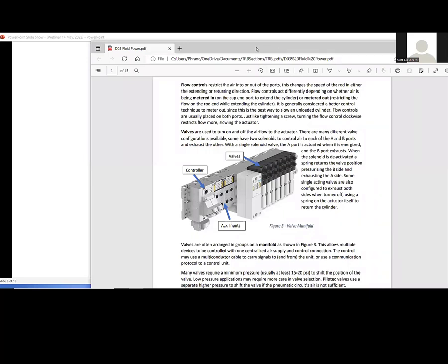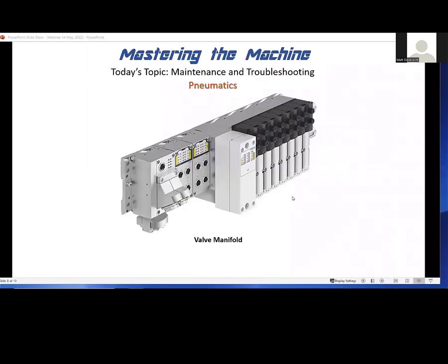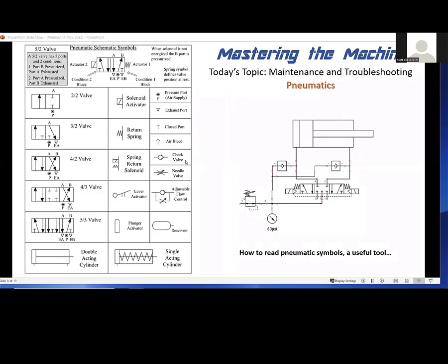So that's a cool kind of valve bank because you can get inputs and outputs from it at the same time. These are pretty common nowadays, where you have your communications to your IO instead of breaking things apart into multiple signals like this, right? This is a valve bank, and I'll show a closer up view of that. But you can see here, every single pin is exposed on this manifold. This is not a communications type manifold. Every single pin has voltage on it, and that actuates the valves themselves. So that is some of the components in here.